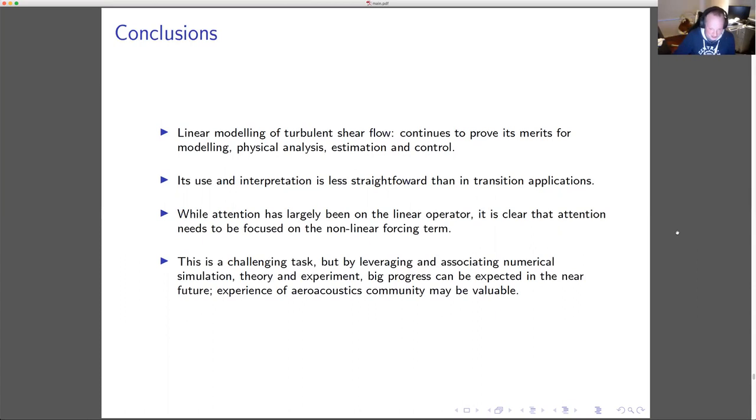Thank you. I see, let me think about that again. It's the mean density, but insofar as the fluctuating density can play a role in the rho u term in the conservative formulation, you possibly have a role from the fluctuating density also in its correlation between rho and u. So you possibly have a contribution from both. Okay, thank you.